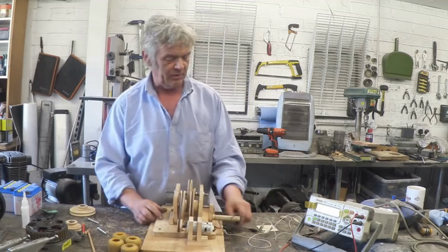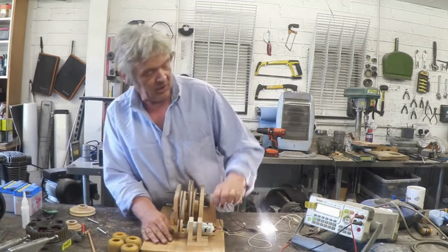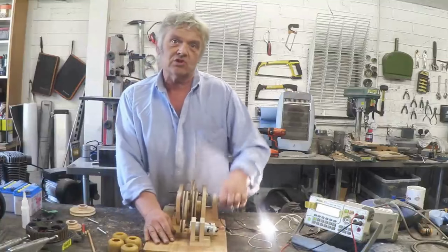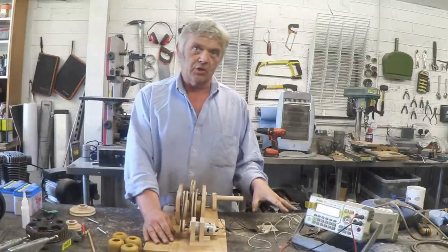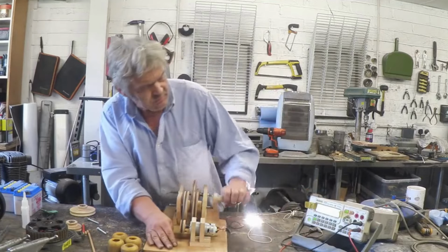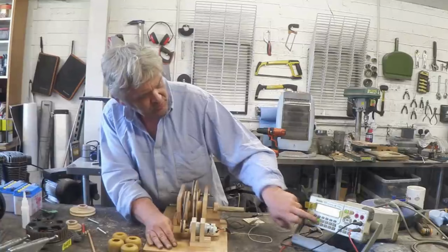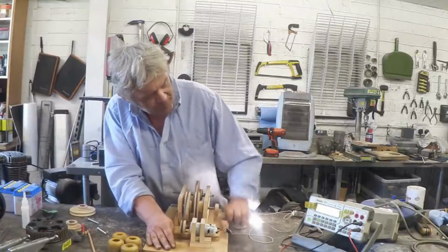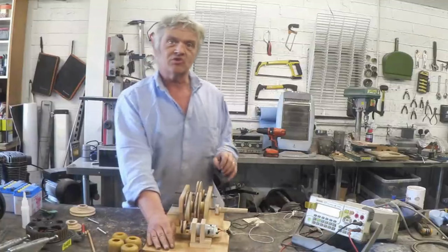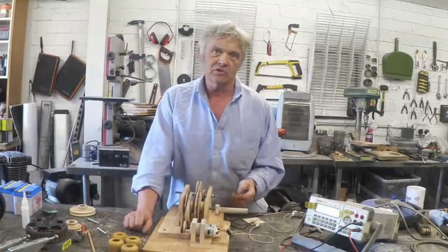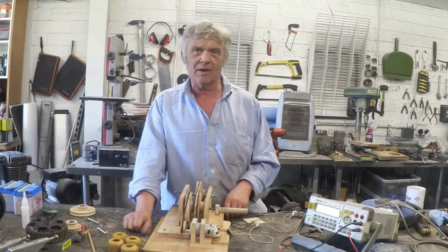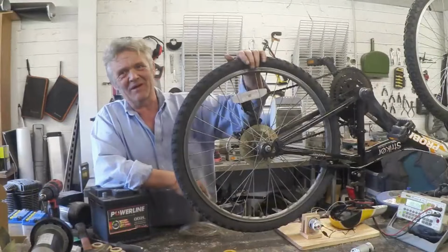Now, if I do that spin up, we'll be able to light that light. There we go. And we're generating about 26 volts while we've got it under load. If we have a look at the amps it's generating, oops, just put it onto amps. Now we're generating about 60 milliamps at around about 26 volts, so it's roughly 1.5, 2 watts, somewhere around about there.